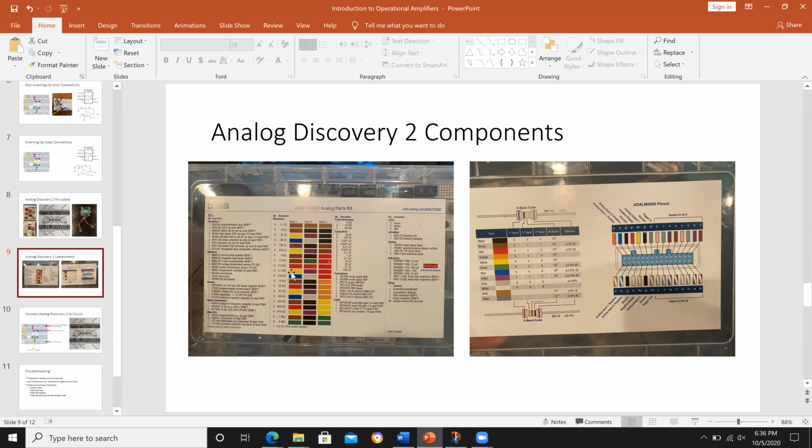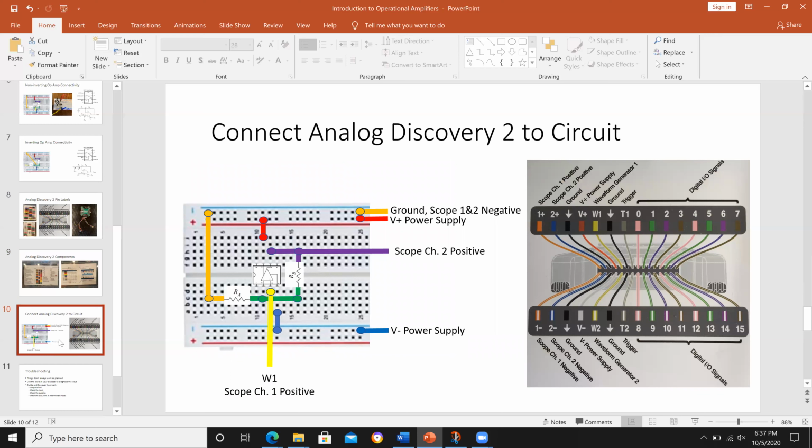The other option, if you happen to have one at home, or if you go to like a Harbor Freight Tools, you could get a multimeter, which honestly I highly recommend. It'll make troubleshooting a little easier. And a multimeter will permit you to perform voltage, current, and impedance measurements on your circuit. And you can pick a really cheap one up for like 10 bucks at Harbor Freight. Now I just want to say that the multimeter is not required. I'm just recommending it as something that could potentially make it a little bit easier for you to perform some of these labs.